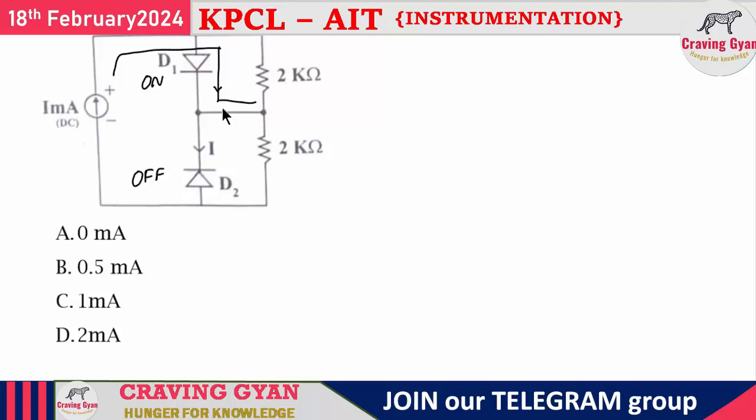Now you will be having 2 paths. One path is through diode D2 and the second path is through this 2 kilo ohms. Now look at the things. High milliampere is the current source. There will be a voltage drop across this 2 kilo ohms, which I take as Vx, with the positive side over here and the negative side over here. That means what?